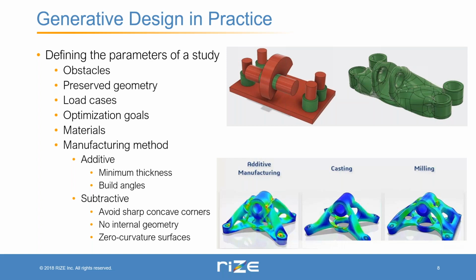For example, it will control things like the minimum thickness that it allows you to produce, and it might design things specifically to use self-supporting build angles so that you won't require as much support removal. These few things don't really affect the ultimate design that much. You can pretty much take full advantage of the optimized topology capabilities with these additive manufacturing constraints without losing much of your optimization of the other features like strength and material usage.